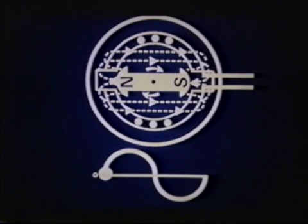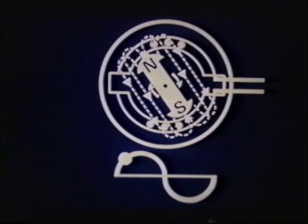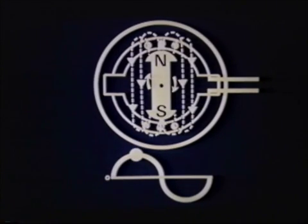On a sine wave graph, the dot illustrates the position of current in relation to the position of the revolving field. Now, as the field, rotating in a clockwise direction, enters the armature coil, cutting of lines of flux starts. Notice the movement of the graph. In this position, we have maximum cutting of lines. This is the peak position for current flow, as illustrated by the graph.